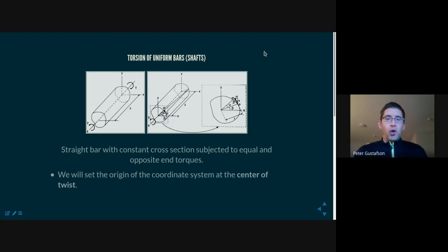Well, now we'd like to look at torsion of shafts and make similar arguments. If we're able to make similar arguments, we will obviously simplify the deformation calculation for a torsional shaft as well. In both cases, if you can write these equations for deformation, then you can easily differentiate to get strain, apply the constitutive law to get stress, and then evaluate boundary conditions. It's always easier to differentiate than integrate, and that's what makes these engineering theories easier to use.